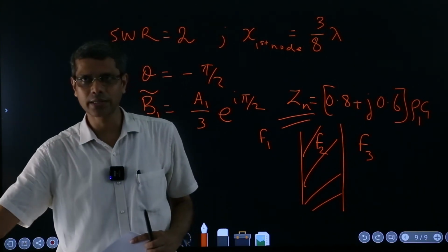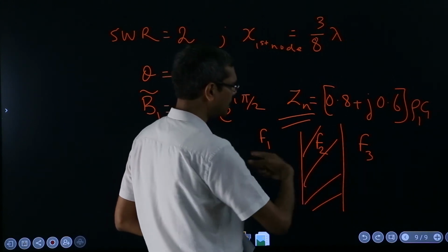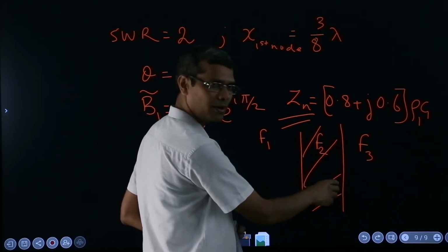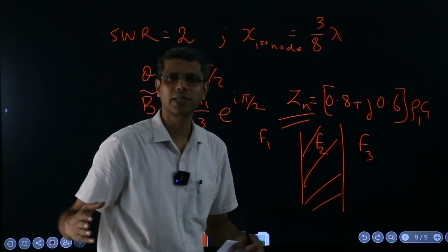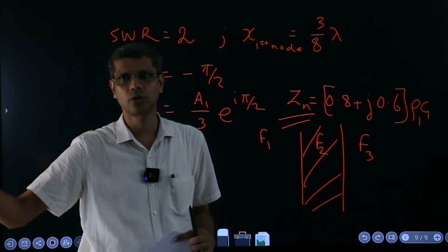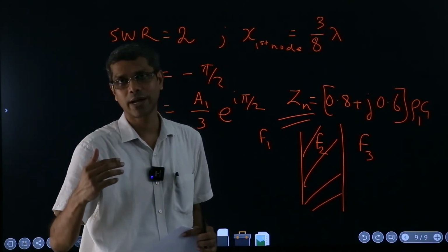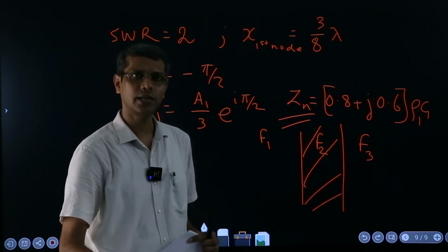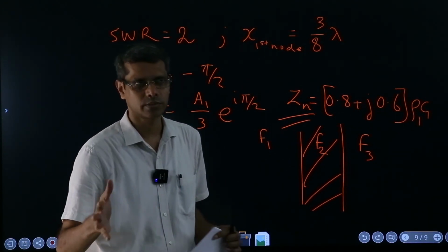So we will have finite thickness of the wall. If we understand this phenomena, we can replace this solid as an equivalent fluid, and talk about the transmission coefficient and reflection coefficient of these finite thickness walls. Then you can predict, if some sound field is existing here, what will be the sound field in the adjacent room if a particular wall is put there.